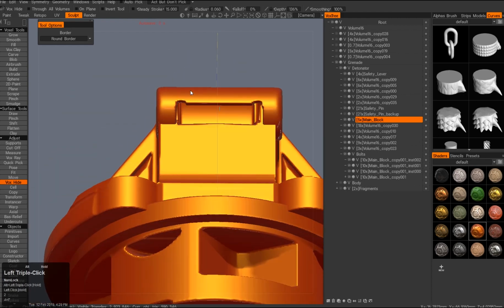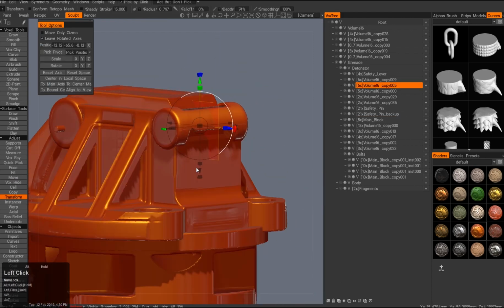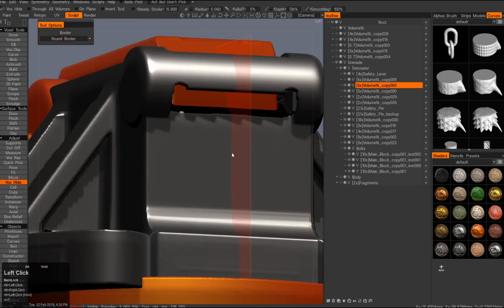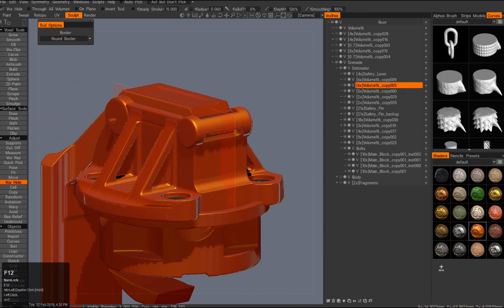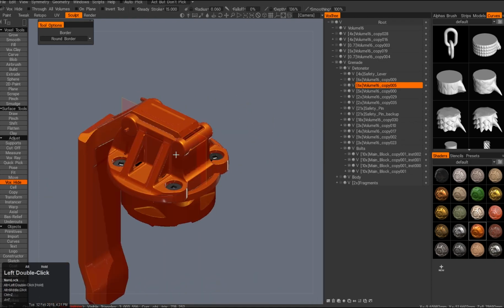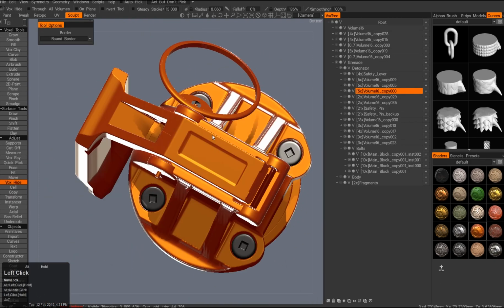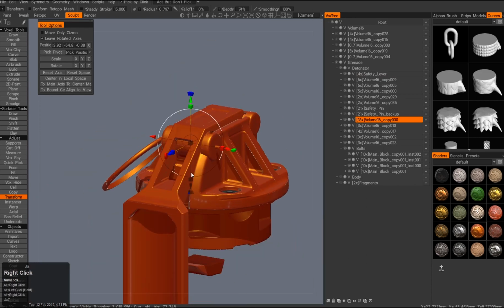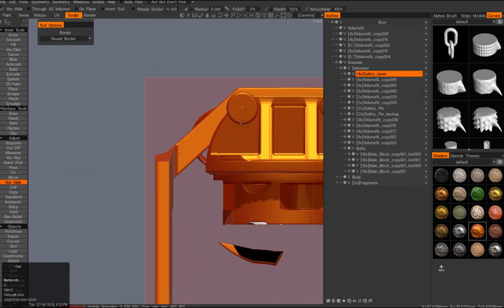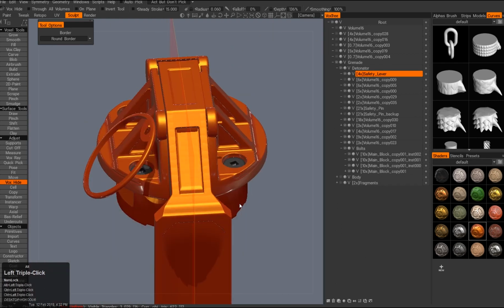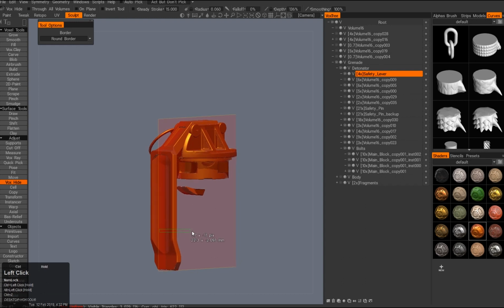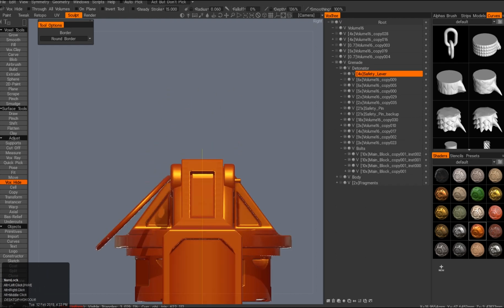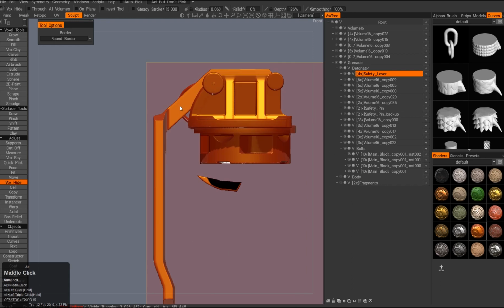So I'm designing that little spoon pin holder right there. And I combine it together with the detonator piece and smooth it out a few times. I constantly smooth it just out of curiosity. It's the F12 shortcut, but I'm really wary about smoothing it, exactly because you can get this type of artifacts if you have stuff that's hidden, and also because you want to smooth the final model. You don't want to smooth it, then combine it with another hard piece, smooth it again, then combine it with another hard piece, smooth it again. It will lead to a problem that in the end of the day you get a super smooth, overly smooth model.